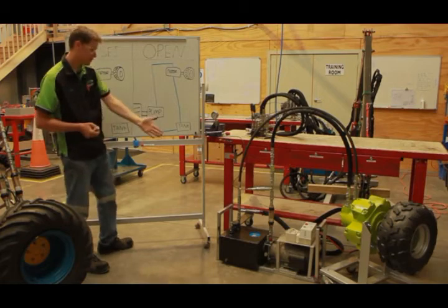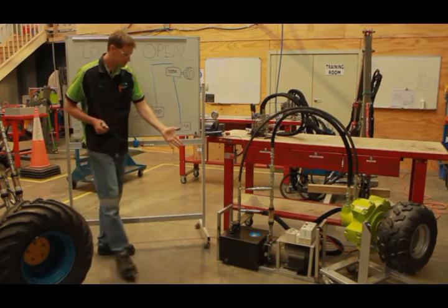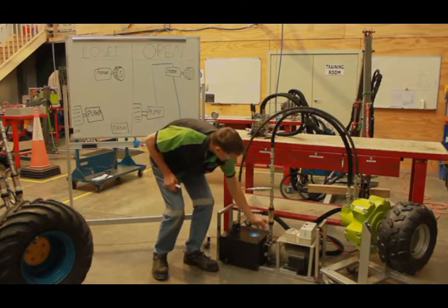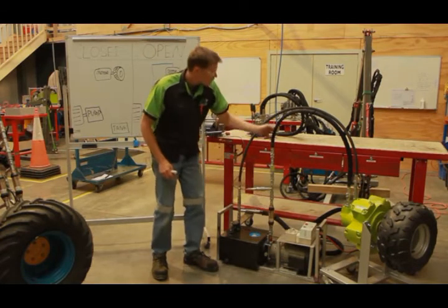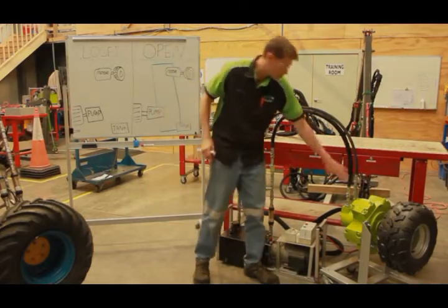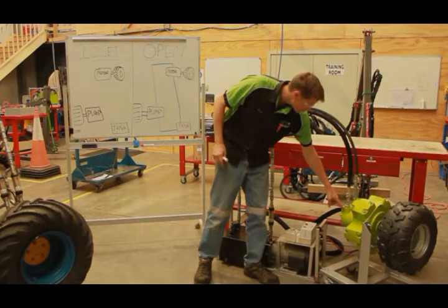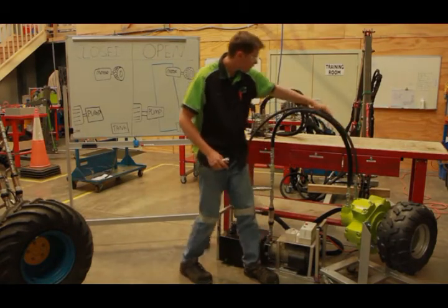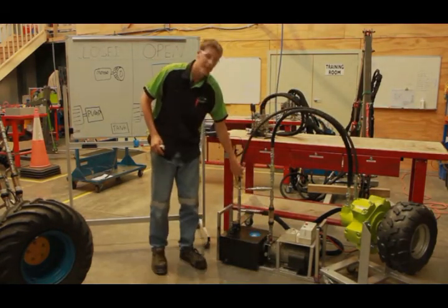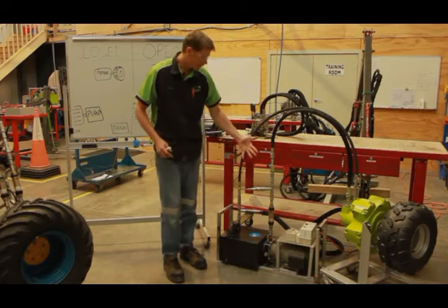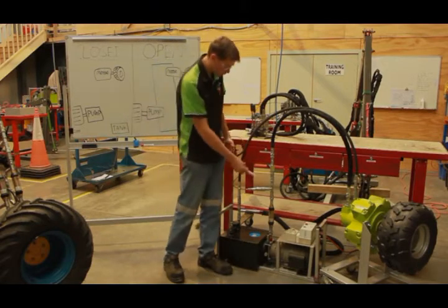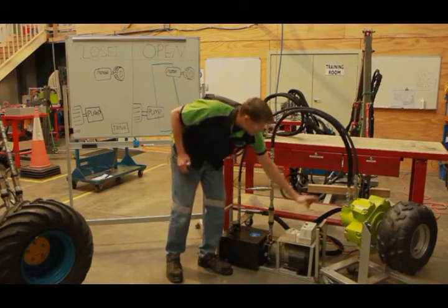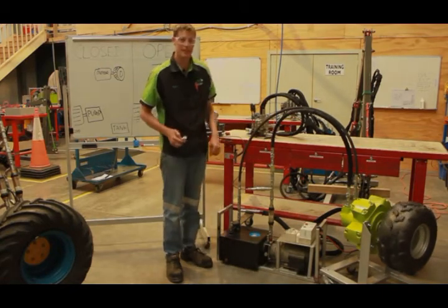And that's what we can see with this particular unit that I've built here. I've got my hydraulic pump which is mounted down the bottom here. The oil from it will come up through this hose around to my hydraulic motor. It goes into the motor, activates it, comes back out through this port, back around and into the hydraulic tank. Now if I start this up, I would expect to see the pump oil flow come through and start turning that wheel. And we can see that that's now happening.